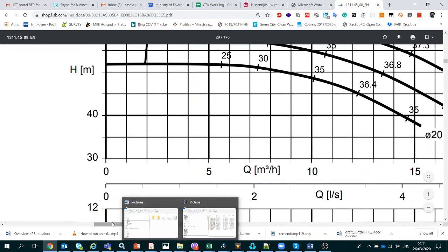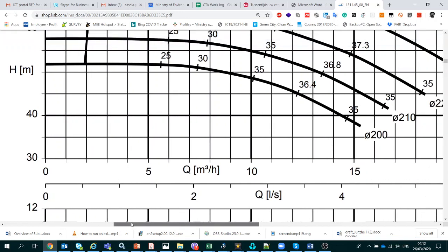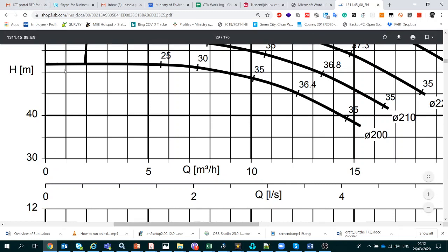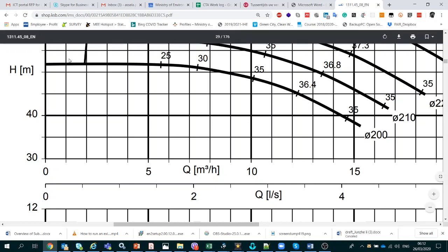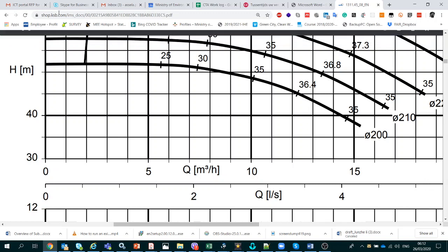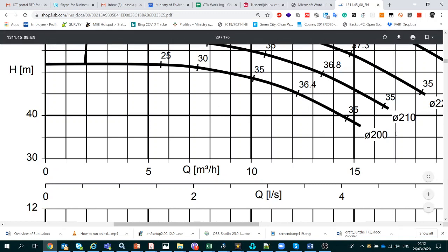When we provided the pump curve to EPANET, what we did was to try to mimic this thick black line. If you have a manufacturer's catalog like this, then we don't do it just by providing a single point, but we can digitize this curve. That means pick up some coordinates here and there, like different Q and H values, and provide that to EPANET, and EPANET will construct this pump curve exactly as it is.